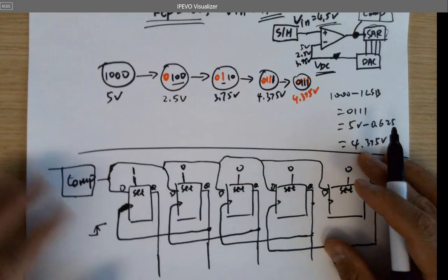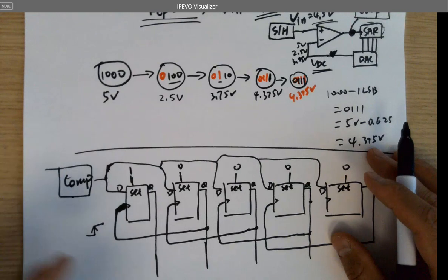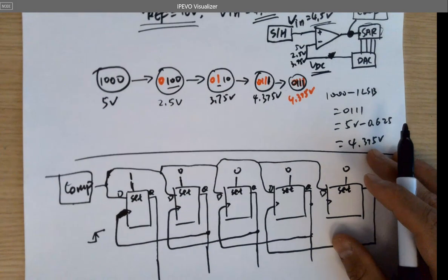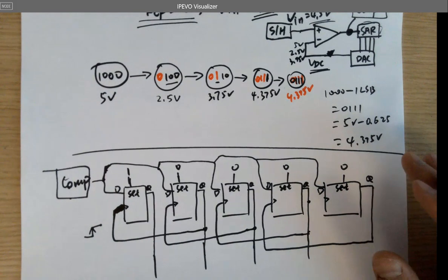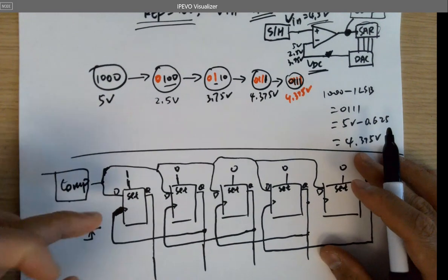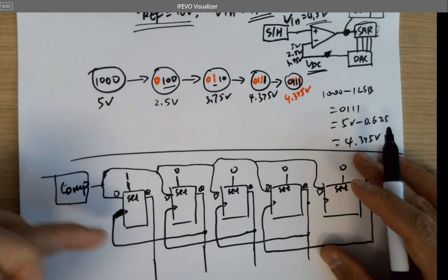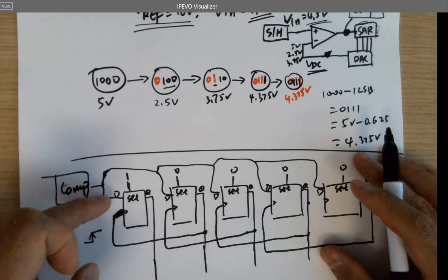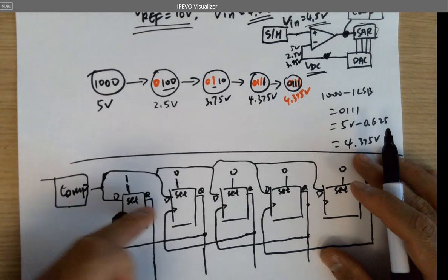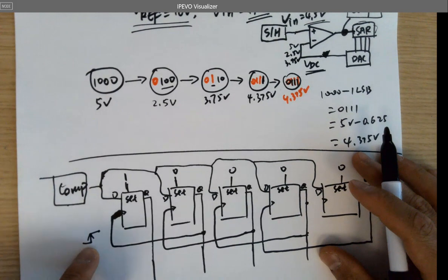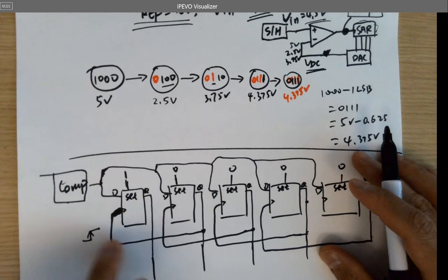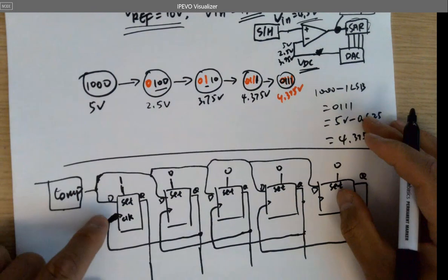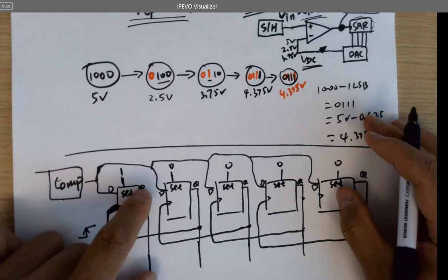It's like a latch, right? Whenever you trigger it, it sends the data from the left to the right. Very simple. It's rising edge triggered, which means whenever it's stabilized at 1, no matter how D changes, the change will not be sent to Q. It only happens when the rising edge arrives at the clock. So these are clocks. It's going to send D to Q.